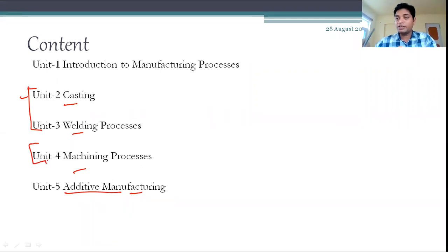Requirement is what, and why is it a requirement? For example, this is the cast material. Initially we think that the final thickness will be 10 mm, but when it is cast successfully, it becomes 12 mm, and this green area is 2 mm. So what you have to do is go for a machining operation. That's why it was a need, this is a requirement.